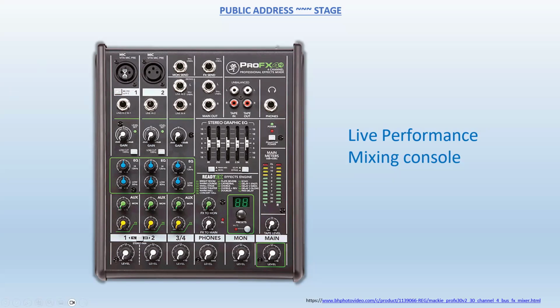So the idea is to have the signal balanced. Now this one here can be balanced or unbalanced, but it's a quarter-inch. It's a semi-professional mixing board, so it's ready for whatever comes at it. Okay? And each channel will have something that is called a gain control. Because different instruments produce signals with different strengths, and sometimes the spread is just too much. So you are making that signal usable for the rest of the system.